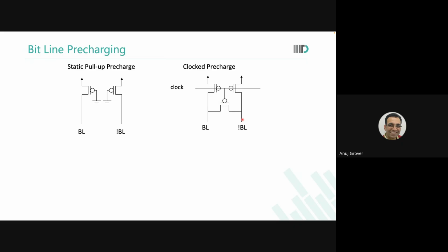So when the read is going to happen, the clock has come, wordline is coming, and you're now waiting for bitline to pre-charge. Tricky situation. You are expected to operate at the speed of the processor. So for all practical purposes, the SRAMs that you will design, you will talk of it as pre-charge happening during reset.